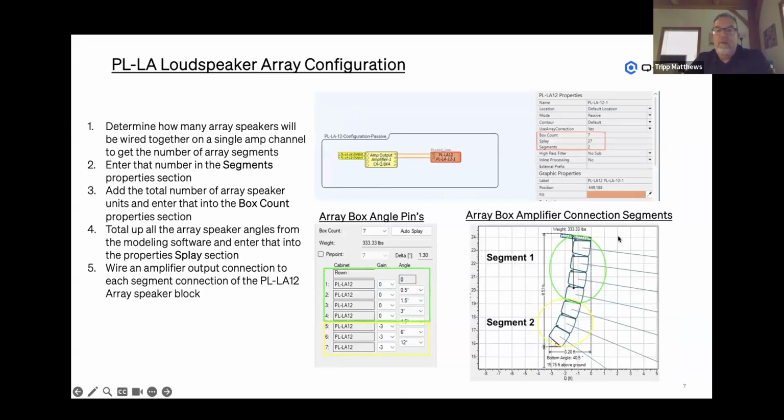When you have a line array that is powered in more than one segment, as we call it, that would be a section of amplifier channels and another section of amplifier channels. And how do you know you need that? Well, if you've been in your EASE Focus and you've turned down or up a section of boxes in the mapping, you've now decided that the first four boxes are on an amp, and then these bottom three boxes need their own amplifier channel so that you can adjust that level. These are passive boxes. So this is what gives you the two segments.